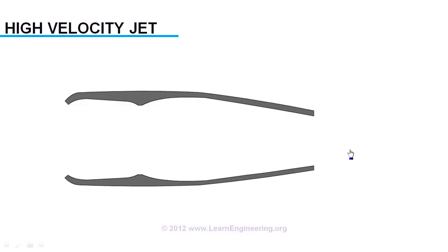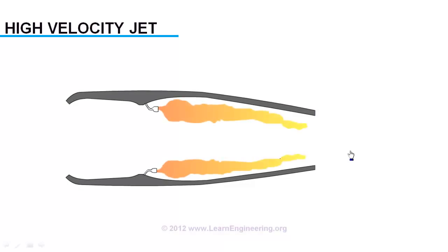We will produce it by a combustion process, by injecting fuel into it, which will produce flames with very high velocity. But for a sustainable combustion process, we need the inlet air to the combustion chamber to be at high temperature and pressure. This is achieved with the help of a diffuser plus compressor arrangement.